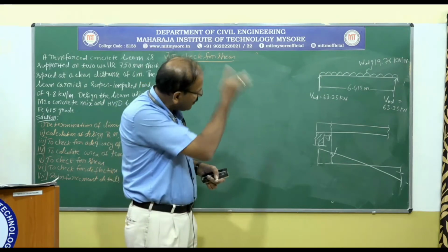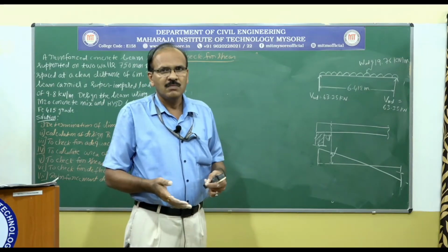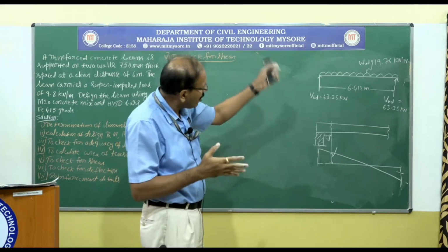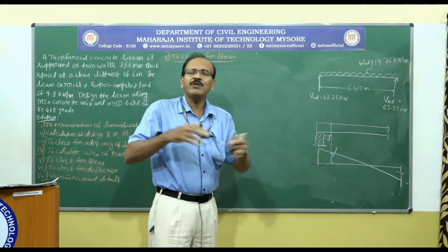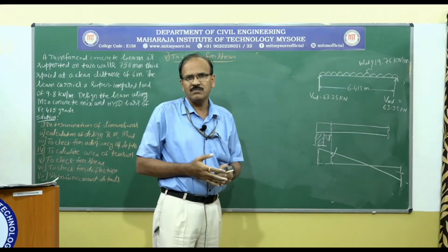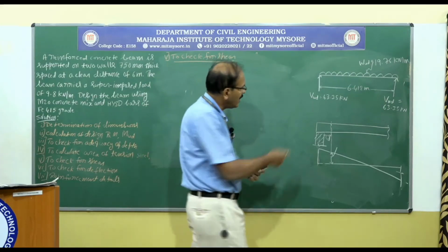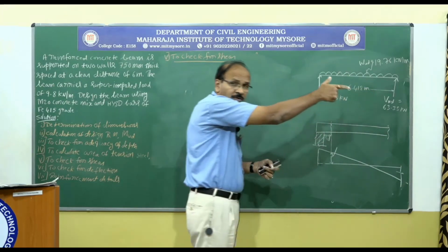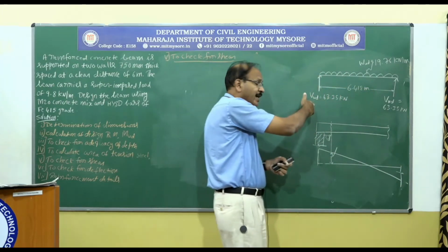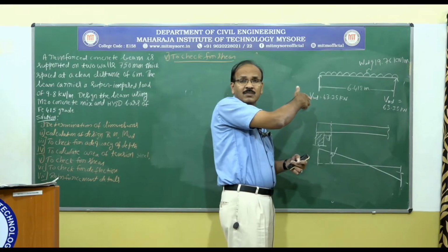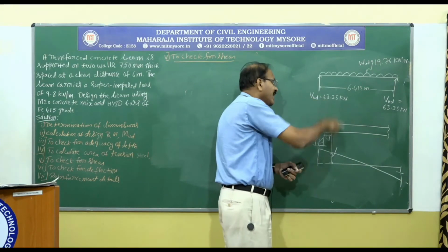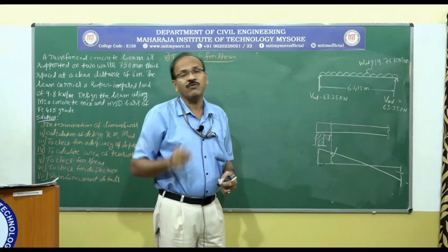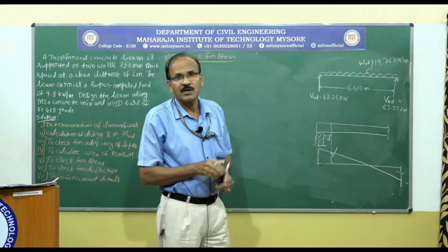So I can go ahead and do everything, but within the given time frame in the examination, if you keep doing all those things, the time will not be enough for you. Just to avoid that, I have taken the effective span and whatever the design load, and I have taken the reaction. Okay, so that reaction is going to be taken as the design shear force. Is it clear to you?